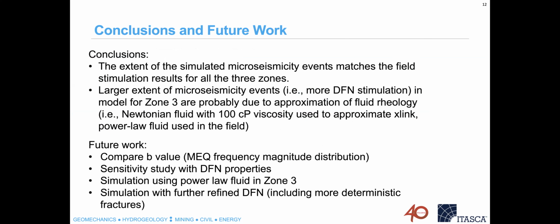So the extent of the simulated microseismic events matches the field stimulation results for all 3 zones. The larger extent of microseismic events in the model for zone 3 is probably due to the simulation of fluid rheology, like the Newtonian fluid at 100 poise viscosity. We use this high viscosity to approximate the field fluid used in the stimulation.